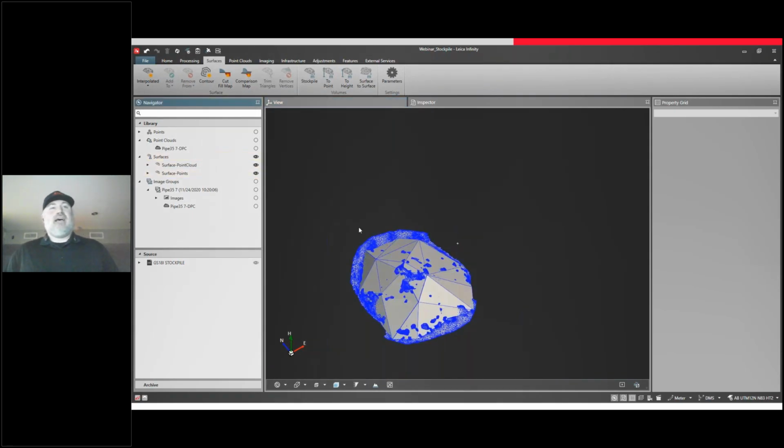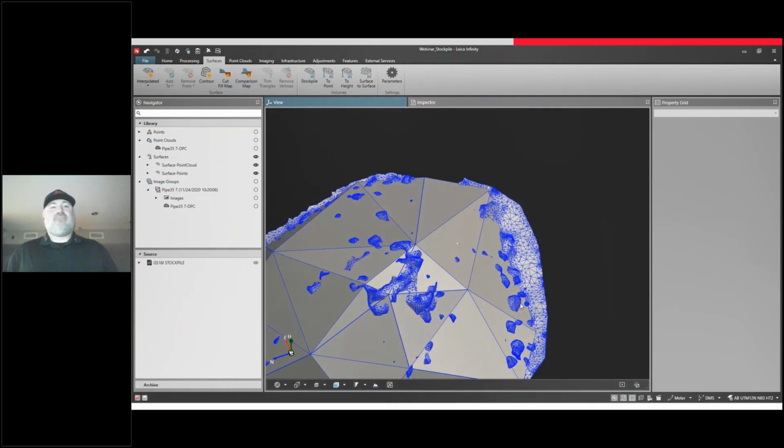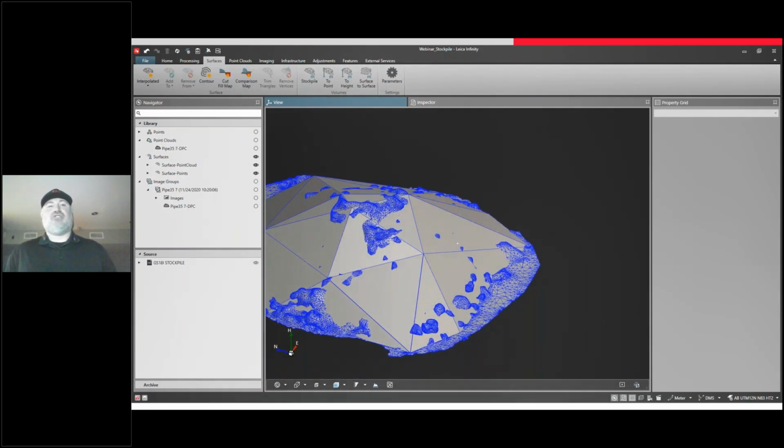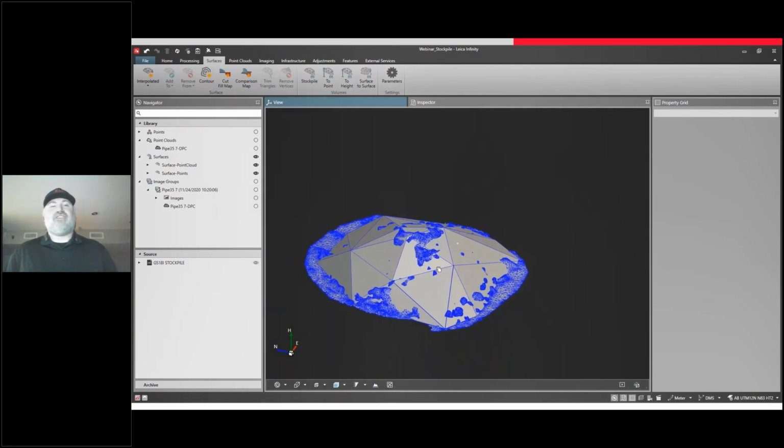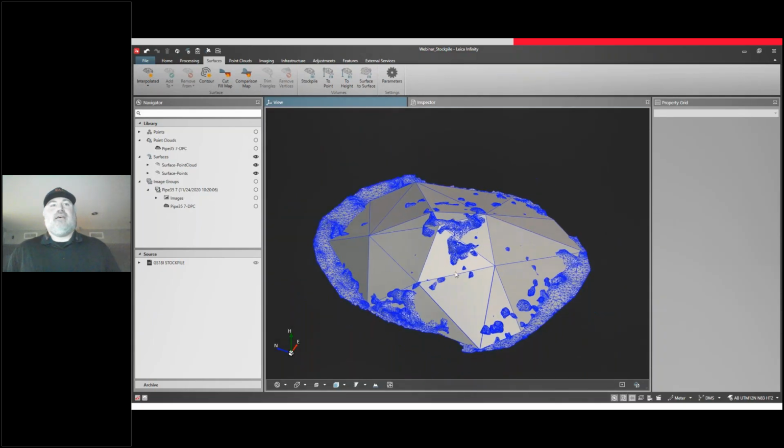All right. I'm going to turn on the original surface from points. And you'll notice here that we can compare the two, just visually. And you'll notice that the initial surface from points is just an estimation of the actual surface. We'll turn off this surface from points for better visualization. But even with the surface off, we can still use the data for calculations.